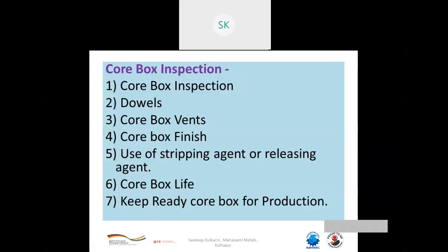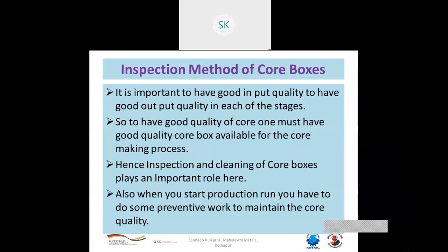Core box inspection includes doweling, core box vents, core box finish, use of stripping agent, core box life, that is tool life, and keeping the core box ready for production as per the planning, so that there should not be any hurry or urgency coming up. So we'll start one by one.